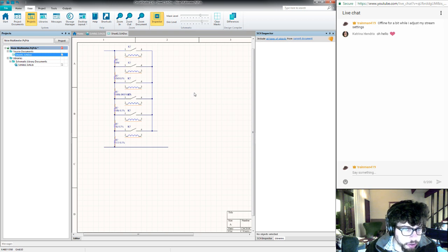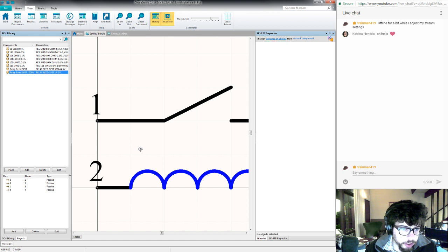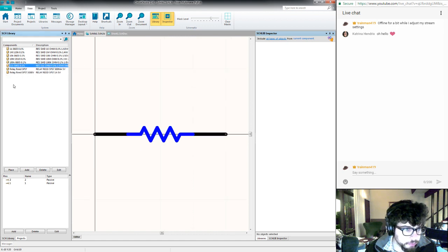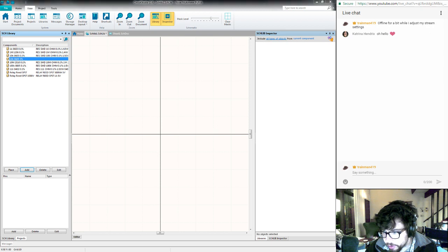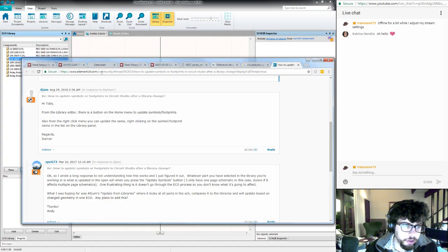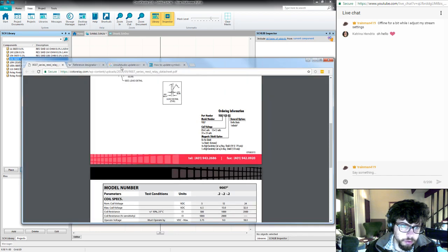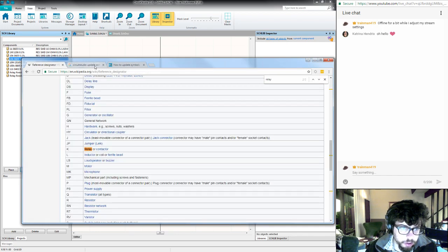So with that in mind, I need to go find myself a 10K resistor. I think I'll use 10K 0603. And this can be a standard 5% part. Let's go find one on DigiKey. I might need that again.